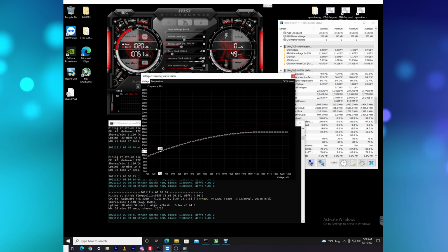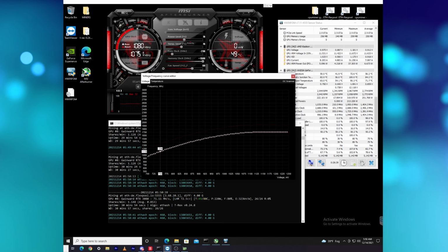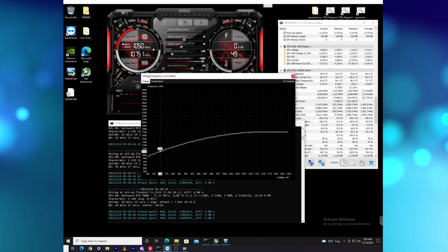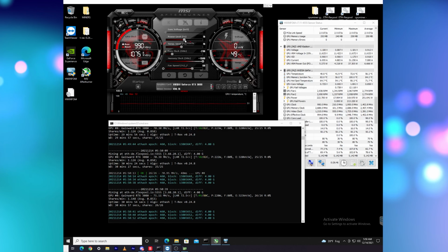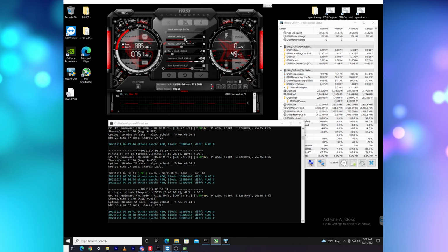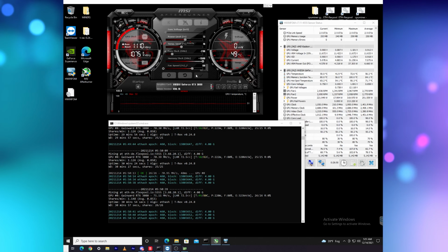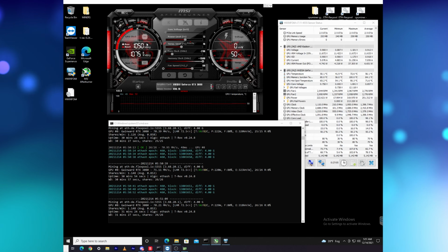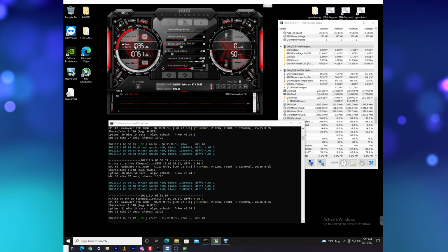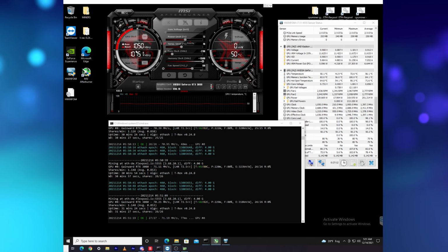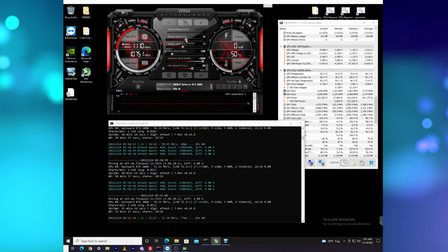And we are just seeing variation between 840 megahertz all the way up to the 1100 that we are asking from it. So now we should definitely start increasing the power limit to arrive and find stability once again. So let's try 72. Even with this slight increase, we're still seeing some slight variations, not as low as before. Before was 840, so right now we're seeing a low of 1050. So we should definitely increase it a little bit more.